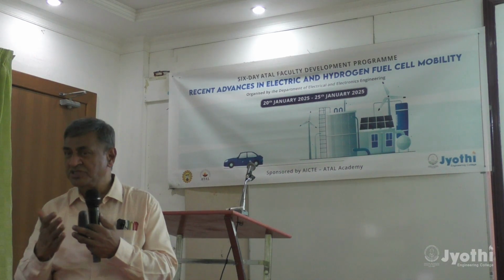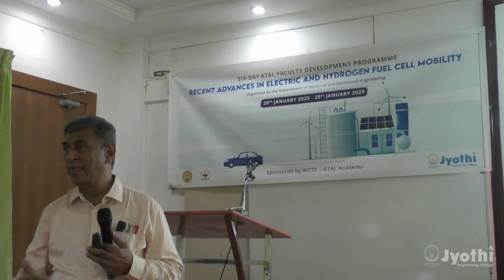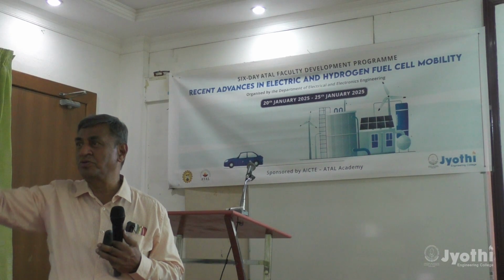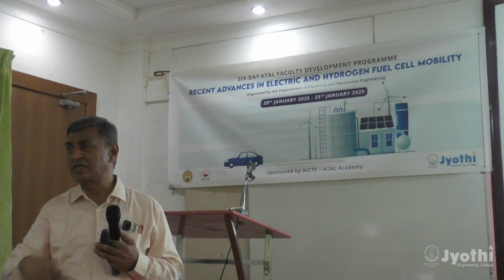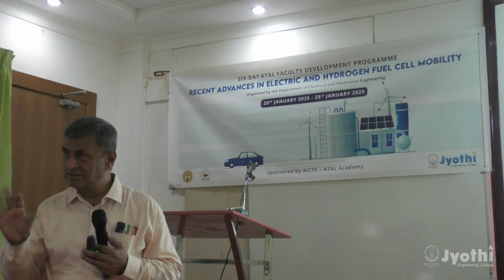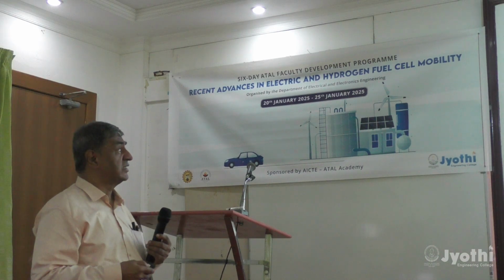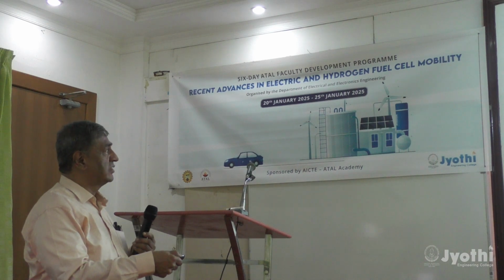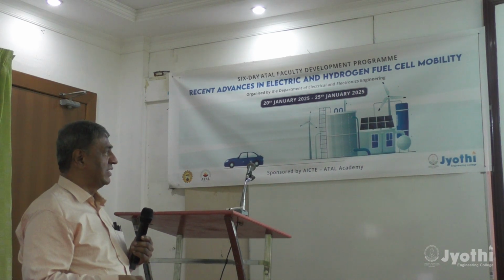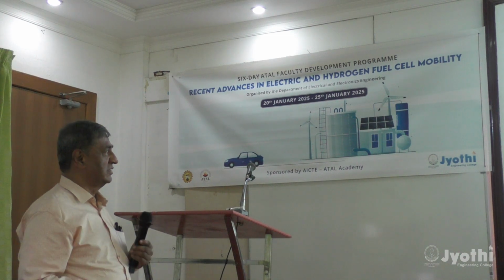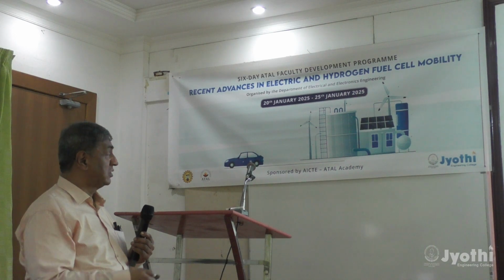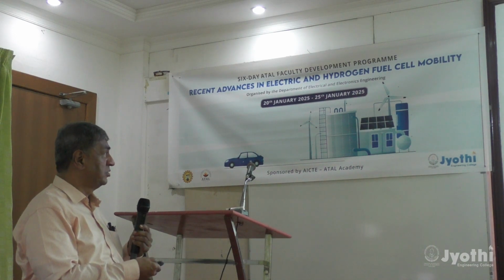So somehow we must be able to separate this electron and electron hole and provide good conductivity for them to get conducted towards, see, the positive charge eventually should go to, let us say, the cathode side, and the electron to the other side. So we must help the transport also. Those are phenomena that need to be addressed. Recombination needs to be avoided. If it recombines, the effect of this photon is gone. Basically, when they combine back, some heat will get produced and heat will be lost. So we must avoid this recombination and allow for transport of electrons, holes, etc. Those things are to be kept in mind.